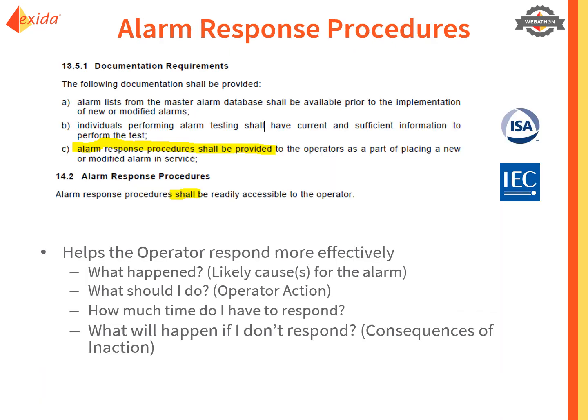associated with the event. Now, the master alarm database can be used to store alarm response procedures. These alarm response procedures, sometimes called AORAs or action on receipt of alarms, are a requirement in the standards. They show an operator how they should respond to an alarm. The standard doesn't dictate how you should present that information, but they do say what information should be presented to the operator. And if you look, you'll notice that the information required by this section of the standards is exactly the same as that for rationalization.